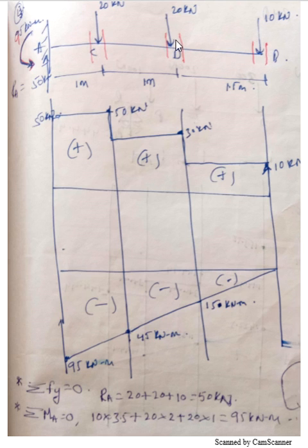Now after this point, if I go to this section, from the right side there are three forces, one is 10, 20 and again 20, but for this force the perpendicular distance is 0, so the effect of this force will become 0. So only consider the effect of this force and this force. Coming from the right side, this 10 kilonewton is bending the beam downward with respect to this section, so minus 10 into the perpendicular distance of 2.5, which will give me minus 25.